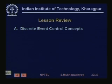So we have the lesson review. So what have you seen? In this lecture we have primarily tried to impress upon you the nature of discrete event control problems. Basically two things: there are some problems where analog controls are not required because they are too simple. If you start a motor for a conveyor, you don't need to control its speed. Just put full voltage, whatever speed it will rotate, let it rotate, the conveyor will move. We are not interested in controlling the speed in an analog manner.